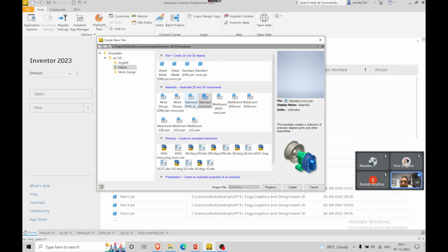If I go here, automatically the arrow is also shifting. So let me keep it on the right side, left side view. Left side view will be our section. So we see the section. If we split the section, it means exactly a plane passing through this center. So we have created a section view.